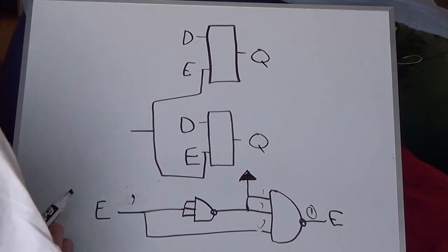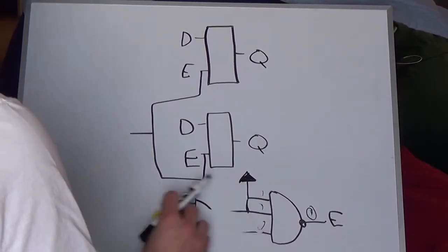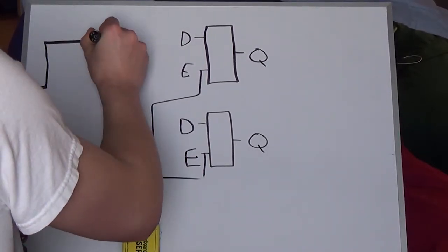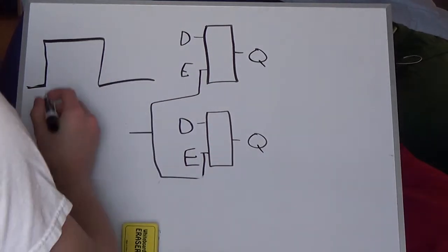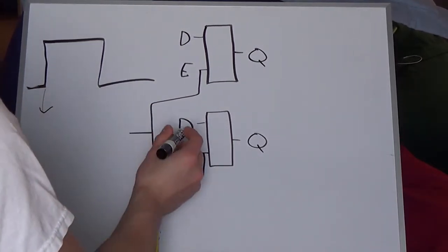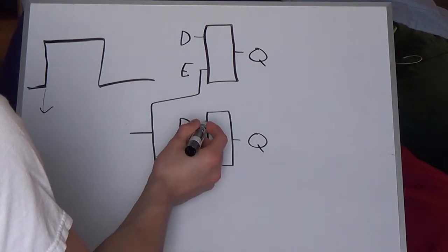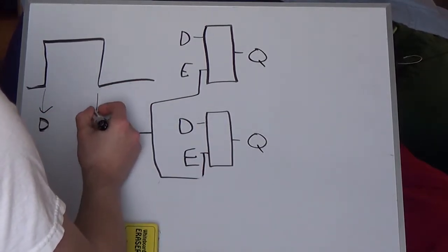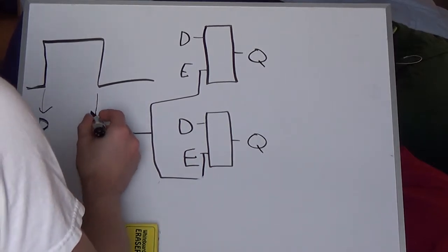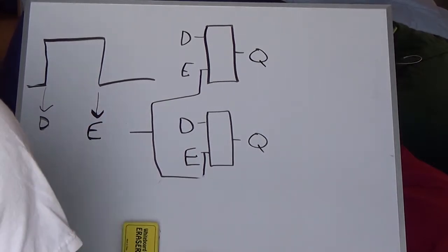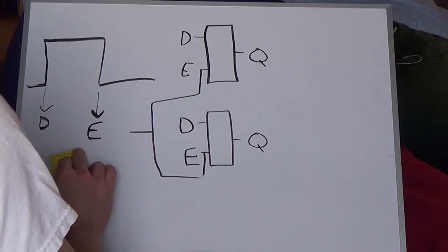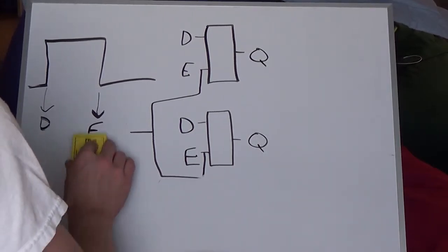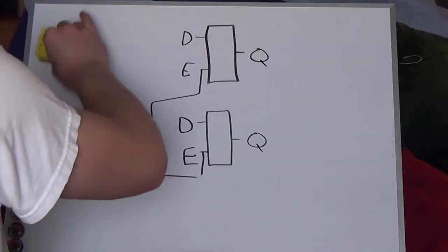And so all I'm doing is inverting the signal going to the positive edge trigger D flip-flops. If this is the signal that will trigger the operations in the computer, this here is when data is pushed onto the inputs of the positive edge trigger D flip-flops. This here at the very end is where enable will be triggered. And so enable's triggered after data is pushed onto the inputs of the positive edge trigger D flip-flops, and that did solve my problem.